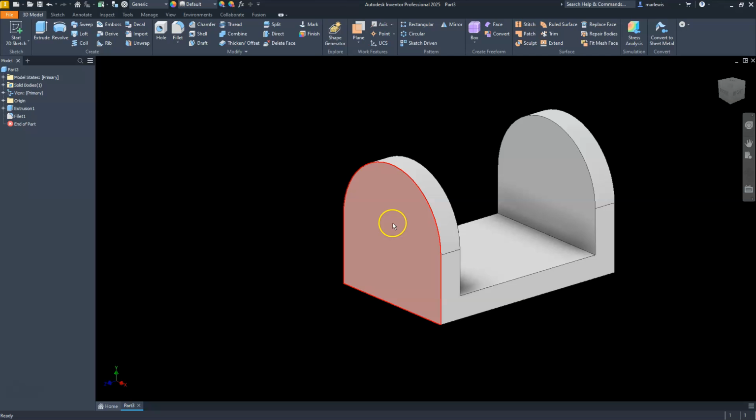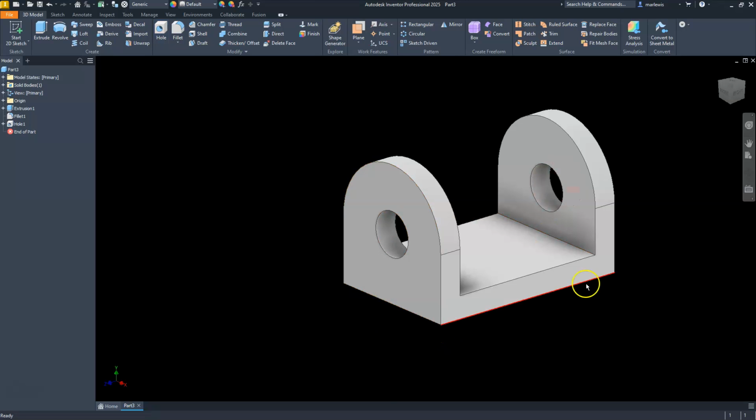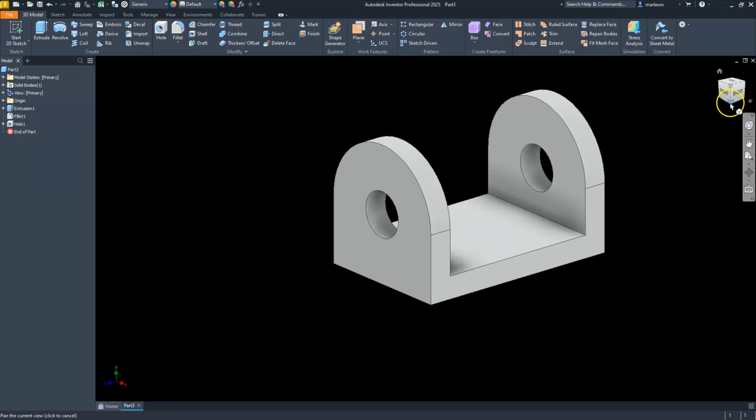Alright. I can also go ahead and put the hole that is running through here. So I'll go to the hole command. And the way this works is that I can start off by selecting the face. Then I can select the concentric reference to it, which is that circle there. And then I'll give it a diameter. In our case, it's going to be set to 20. And it's going through all. So therefore, that icon should be checked. Let's go ahead and hit the OK button. And the top half of this one is created. Let's kind of look at the bottom part of this.